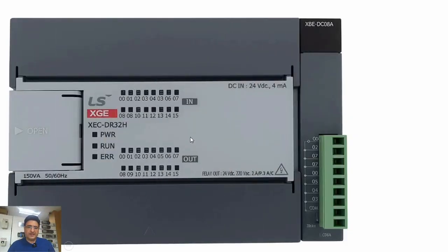So here we have an LS PLC, and we've added an input expansion card to it. And now we want to assign an address to its input number 5. We use the address %IX0.1.5. The 0, as we said, indicates the base, and it's always 0 in compact PLCs. This one, as we said, is the slot number, since here we've added an expansion card. We've entered the slot number here. And this 5 is the terminal number of our expansion card.